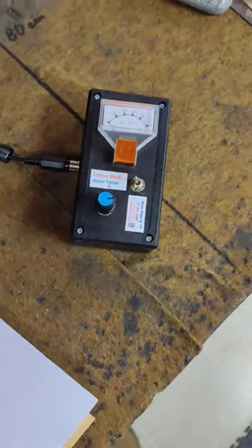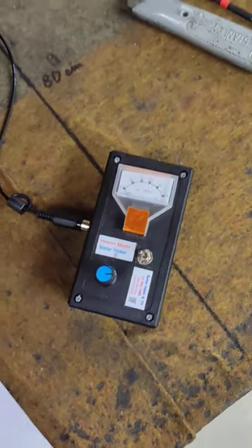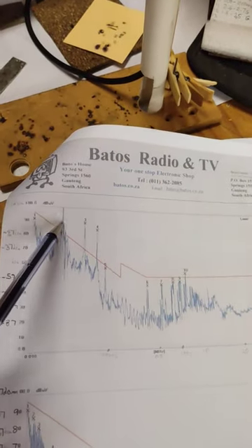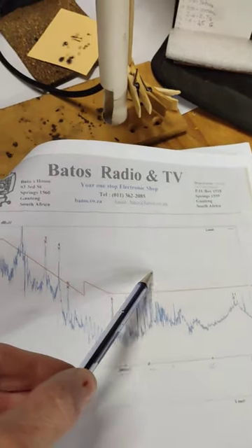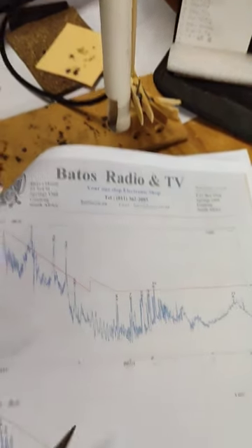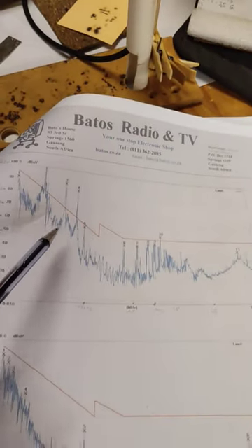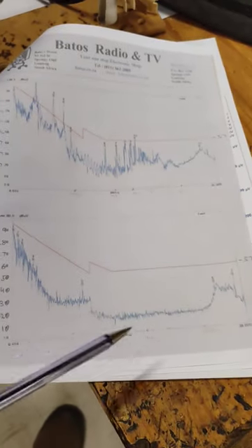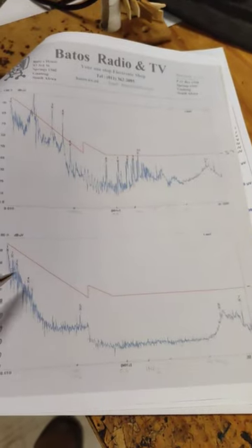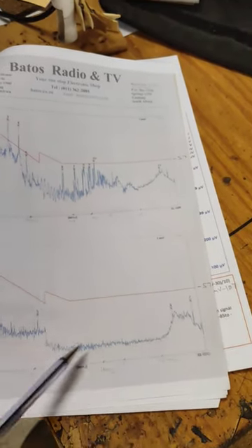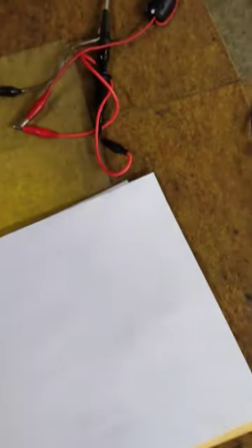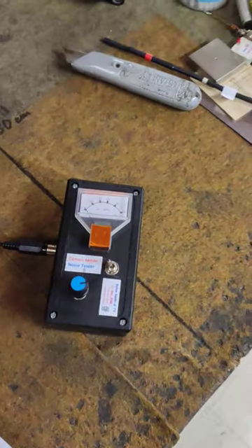Now with the common mode noise filters, you can never really, as I said, kill it 100%, but the idea is to bring these spikes, or the actual noise above the red line, to just below the red line. And luckily with this particular filter that I have captured the measurement of, I have managed to reduce it substantially. So it depends how much the customer is prepared to pay for the filter and things like that. On that note, let's start again.